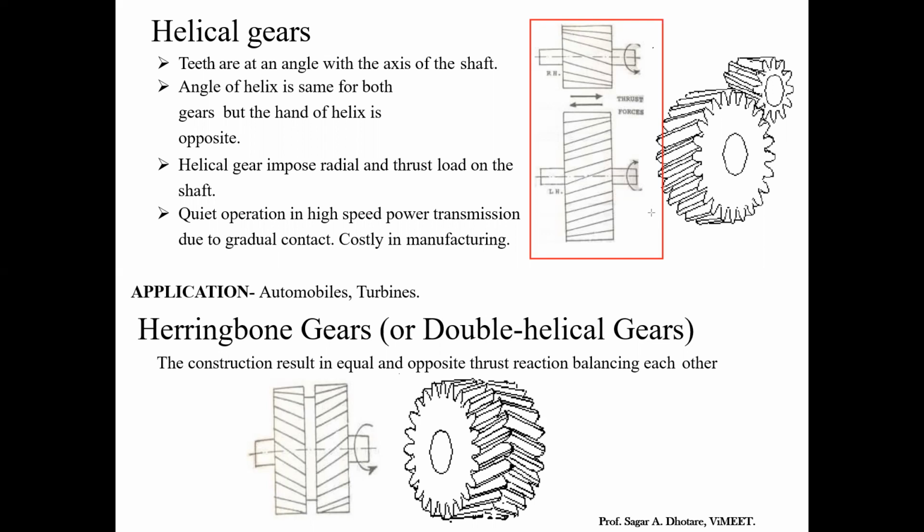In a cross helical gear, the gears are normally used for transmitting motion between two non-planar and non-intersecting shafts. In cross helical gears, the pinion and gear may have the same or opposite hand of helix. In cross helical gears, the contact between two meshing teeth is theoretically a point contact. Hence, cross helical gears are not preferred for power transmission, because they are used for motion transmission only, not for power transmission.